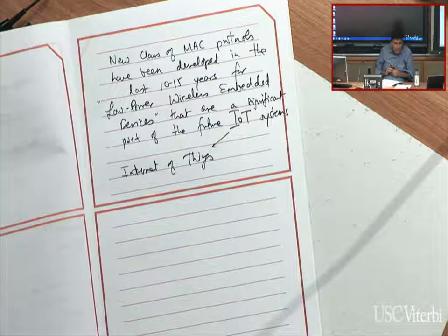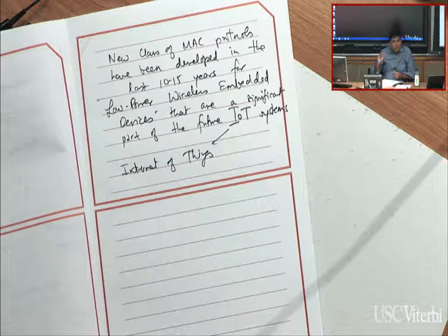The best example of it commercially that's already been very successful for a long time is like the Nest thermostat. Right? It's a device that's in your home that's monitoring temperature, it's monitoring and controlling the actuation of AC and HVAC systems. Increasingly, we're talking about deploying many, many objects in our house and having them be able to communicate wirelessly with other devices. And unlike a lot of traditional wireless nodes, whether it's your cell phone or your laptop, where periodically you can plug them in for power, as you increasingly try to embed your wireless devices and radios in things that are not plugged into the wall, they're running on batteries, you have to be very careful about how much data they communicate, how much energy they use up. And so you have to end up putting them to sleep a lot.